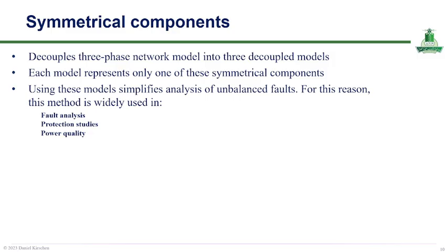This separation greatly reduces the complexity of analyzing unbalanced conditions such as faults in the system, and because of its clarity, this model is widely applied in practical power system studies, including fault analysis, protection studies, and also power quality assessments.